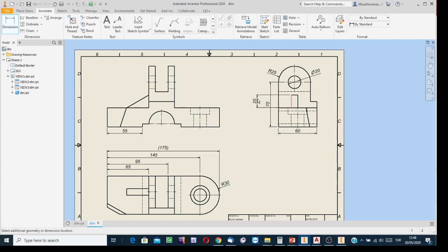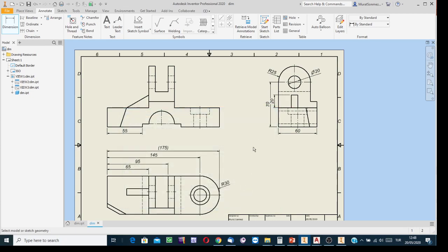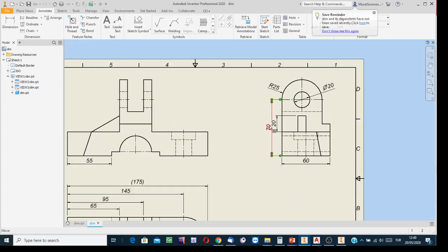Never have such an intersection. If by mistake you show the greater distance first and then the shorter, then they may interfere. Press the escape button, and then hold the dimension with a click and you can move it.